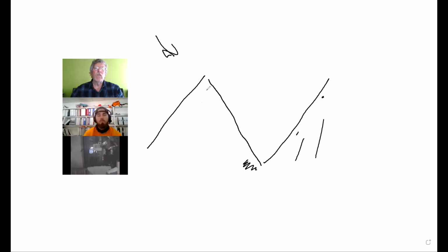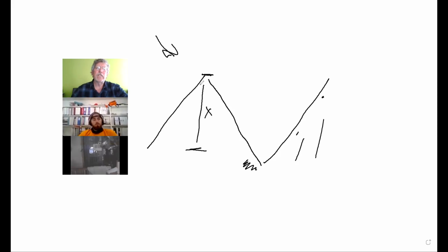So how do we do that? Well, it depends on your latitude, but usually what we're going to say is the distance in this area, whatever this is, the distance here is going to be X. Then we want to set our array back 3 times that distance. So this would be 3X. So if this is going to be, let's say, 4 feet up, then we need to go 12 feet back. It's just a rough rule of thumb for this latitude. You can get more exacting, but it's not going to be far off of that.